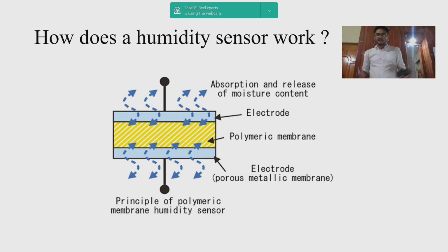There are other sensors like thermal humidity sensors, which are used to measure absolute humidity. Unlike the relative humidity sensors, thermal humidity sensors utilize two probes. One measures dry nitrogen, and one measures the air of the surrounding environment.